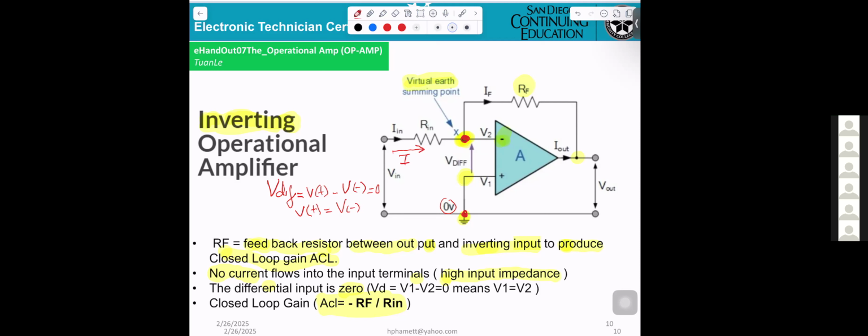Okay, when they go up to the virtual route right here, they cannot go down. The thing is that the same voltage current cannot flow into V2 minus here, because of the high input impedance. So the current now has to flow this way.